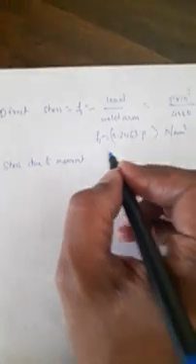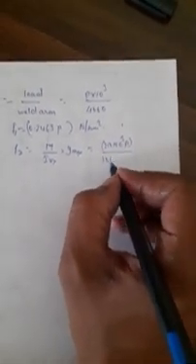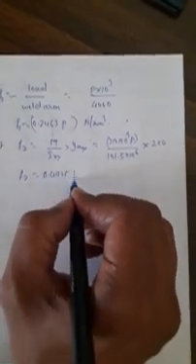Similarly, stress due to moment F2 is equal to M divided by Ixx into y max. So I can write that equation as 250 into 10 raised to 3 P divided by 101.5 into 10 raised to 6, that is I. Y max is 200. So solving this equation, I get F2 is equal to 0.4925 P newtons per mm square.